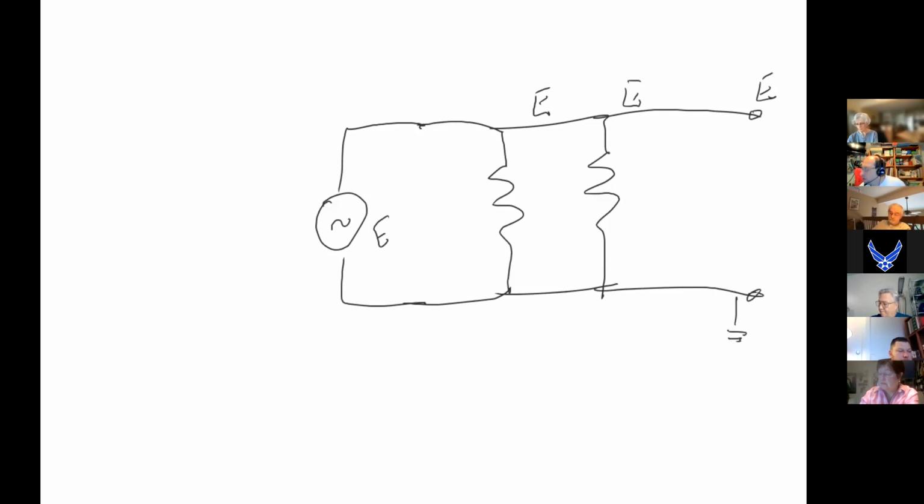Now, what it also means is that this main bus wire right here is going to be carrying all the current necessary to run what? Everything. That's right. Every single thing in your house. So this, it turns out, might be a 15 amp circuit, and this is a 15 amp circuit. And even though there's nothing hooked up, this is a 15 amp circuit. So how much current does that wire have to be able to carry? 45 amps at least.